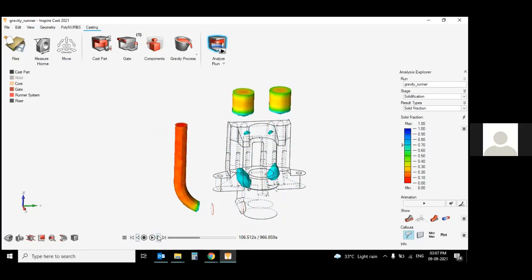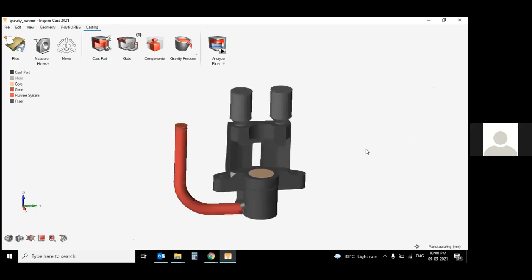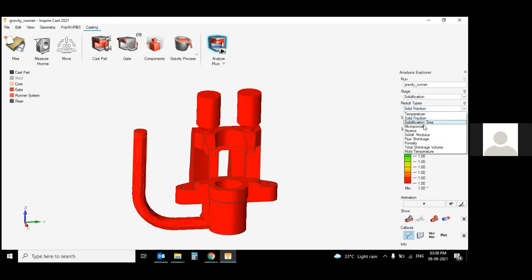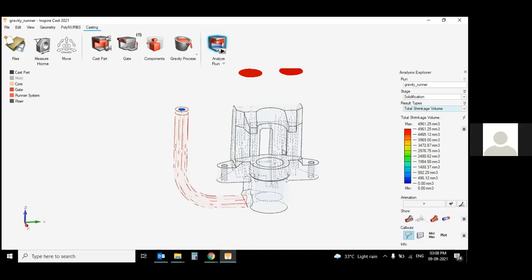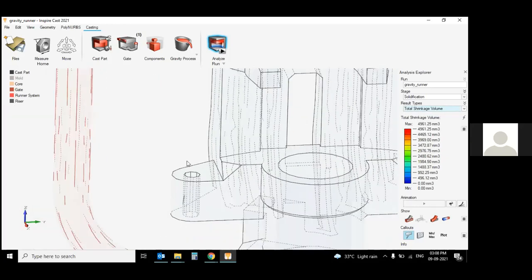These regions solidify at an earlier stage, but the gate, runner and the risers are still in the liquid phase. So your shrinkage porosity has also shifted, also moved. And let's check the amount of just this little pore.